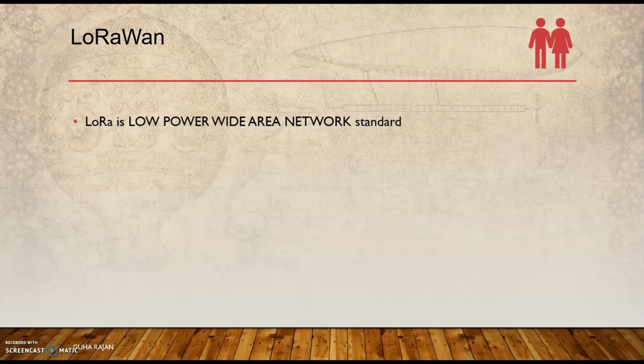One is the power area, the other one is of course the network. You might not have Wi-Fi connectivity. Even if you do, it is not necessary, because all these IoT devices or sensors are just going to send out a byte of information. For example, if it needs to send a temperature measurement of 30 degrees, it's about maybe 2 bytes of information.